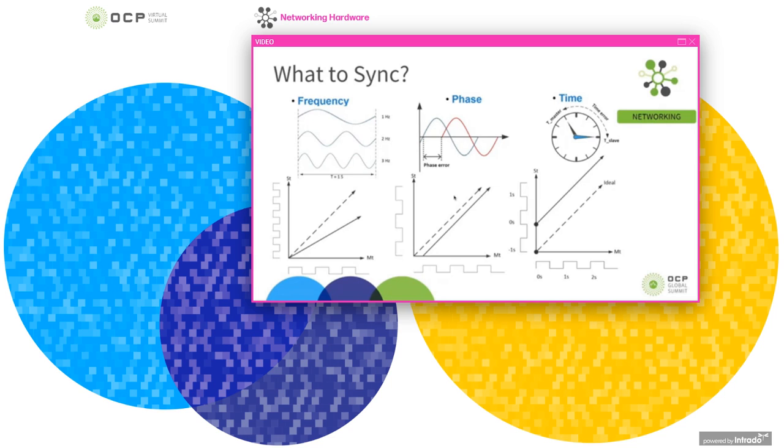And the second one is phase. Here, we assume that your frequency is fully synced. But now you will have another problem, that is, there may exist a phase error. It will continuously live in your system, especially when you need to cascade many nodes together. So the phase error will accumulate through many nodes cascaded.